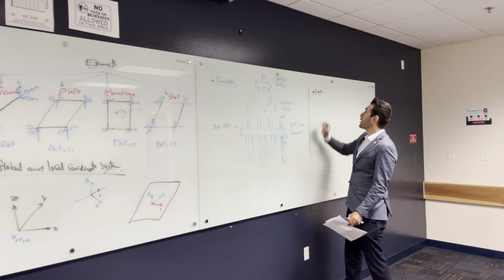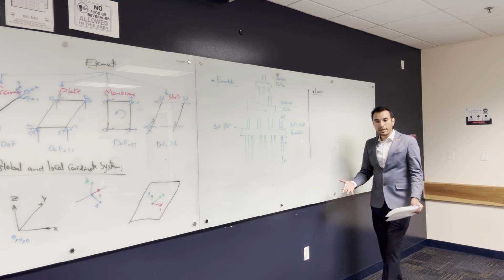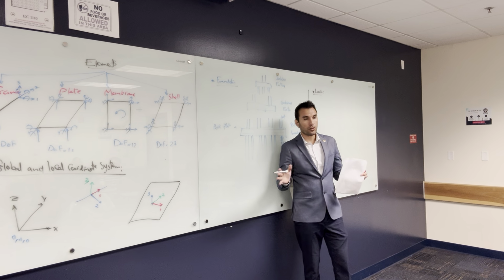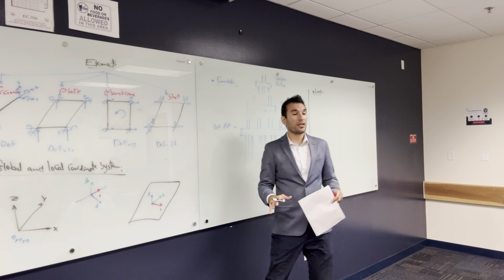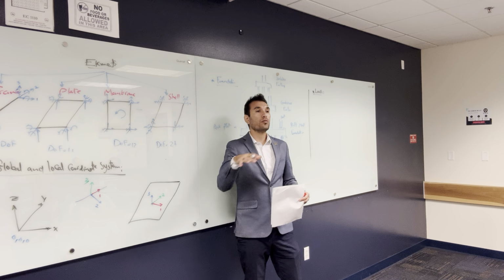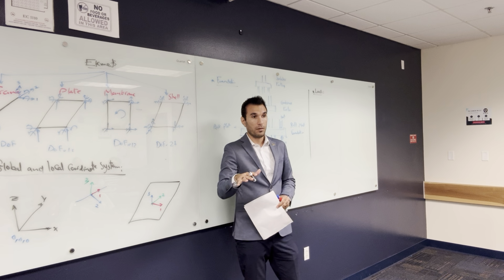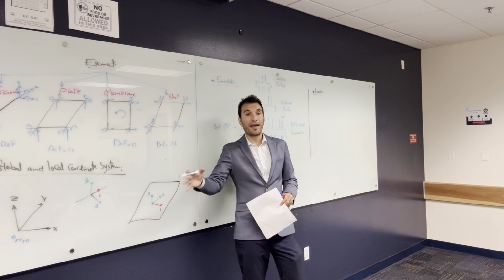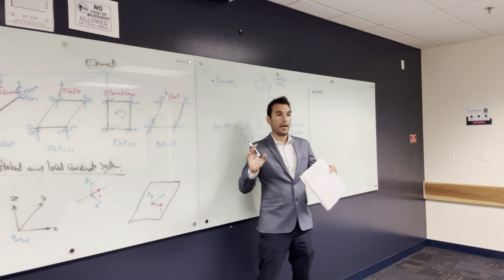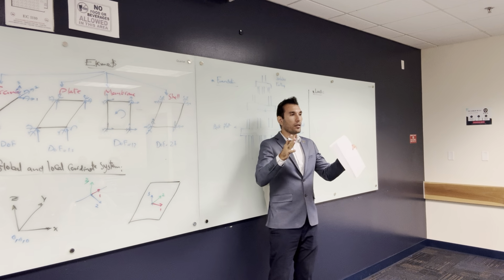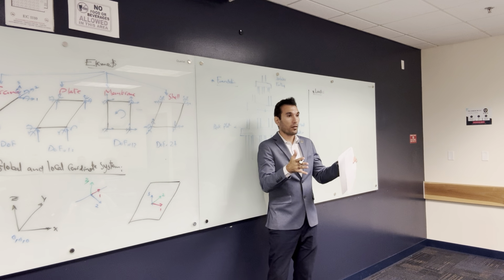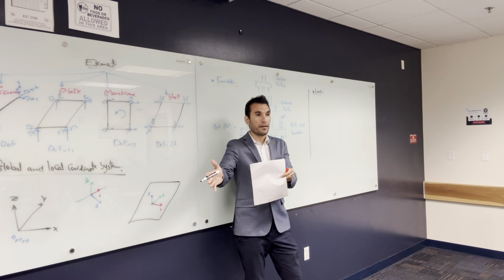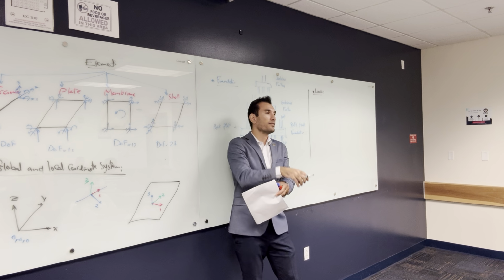loads. So for loads, the thing is, if you are drawing a real structure, like you are a structural engineer in a structural engineering firm, and you are going to design a building, I usually have the own weight inside the dead load, and I don't touch it. And I let the software calculate the dead load for me. And I make the dead load factor equal to 1. Like, I ask the software, hey, I'm making a load case. This load case is called dead load. And calculate the own weight of the structure based on the density of the material that I gave to you, and assign this own weight in the dead load.